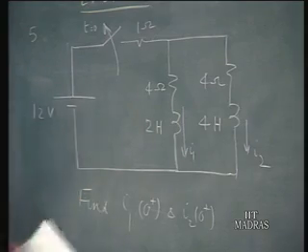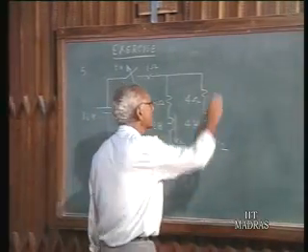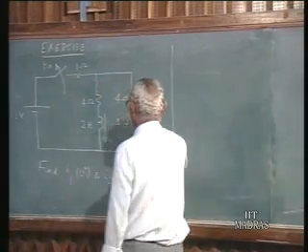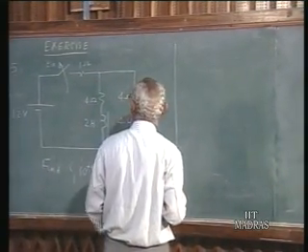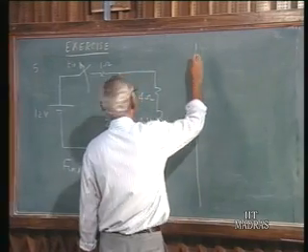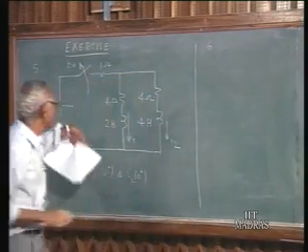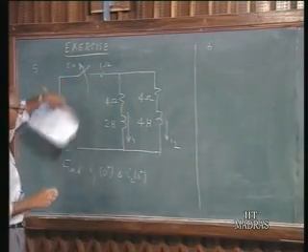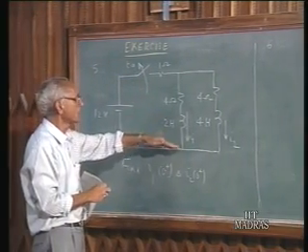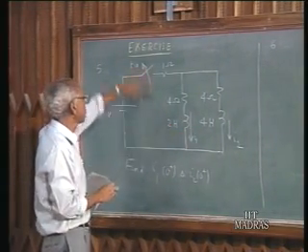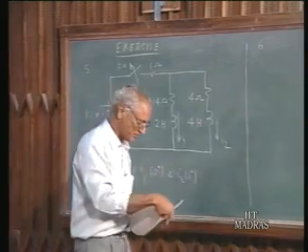This is an illustration of the situations where inductor currents can be discontinuous. So using the principles that we have talked about, find out I1(0+) and I2(0+). Assume that initial conditions have been reached prior to the opening of the switch. When the switch is closed, steady state conditions have been reached, and therefore the inductors carry some current. Once it is opened, find out the new currents.